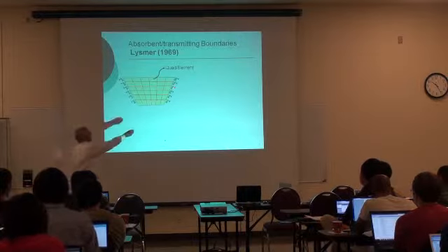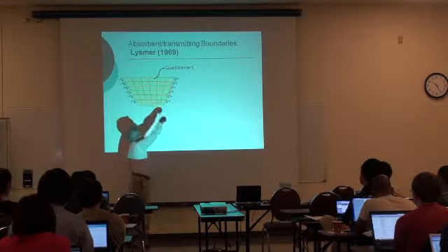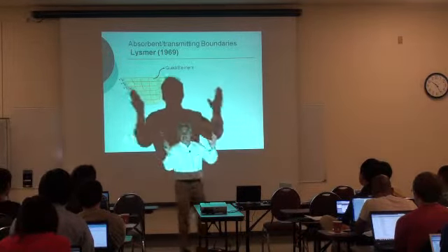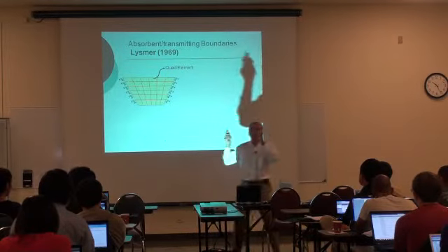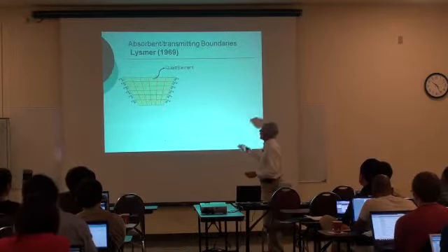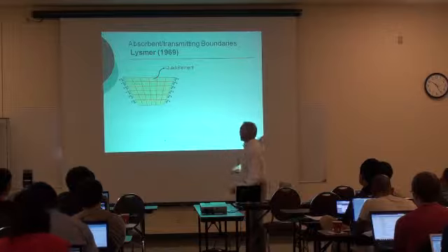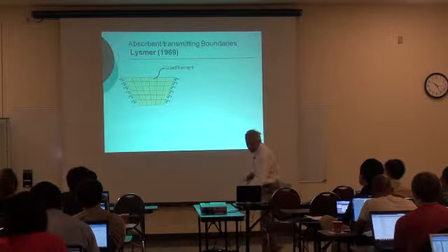The problem with that is that in reality, in the soil, this boundary doesn't exist. That boundary exists only in your model, not in the real soil. So you have to impose some boundary condition that absorbs all the energy that gets there.